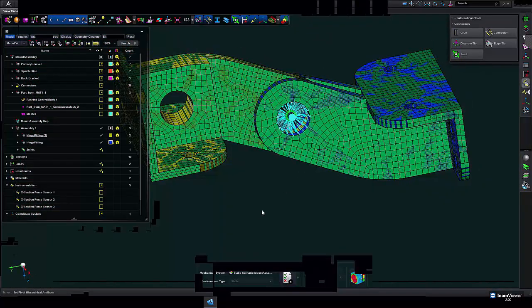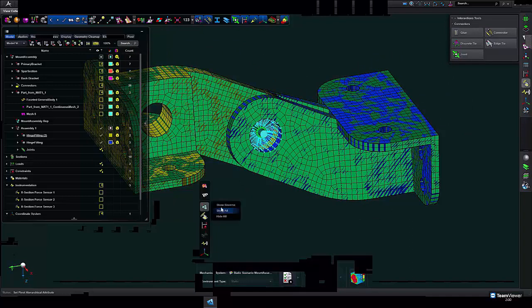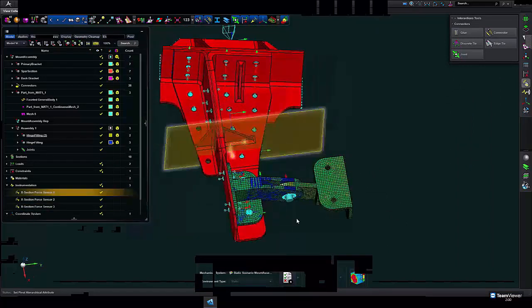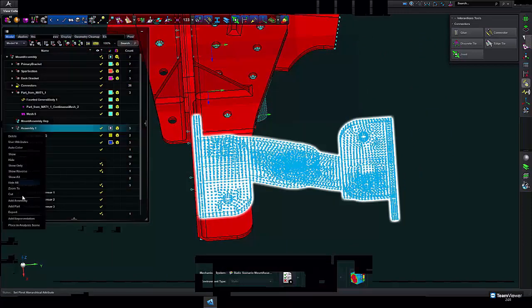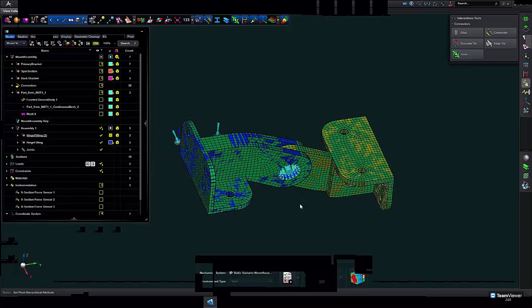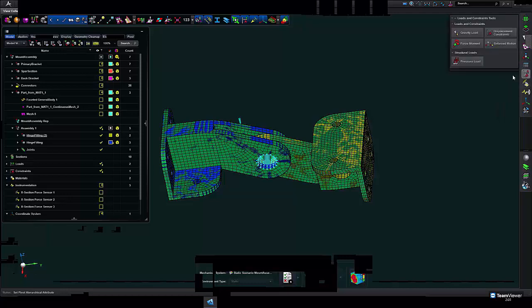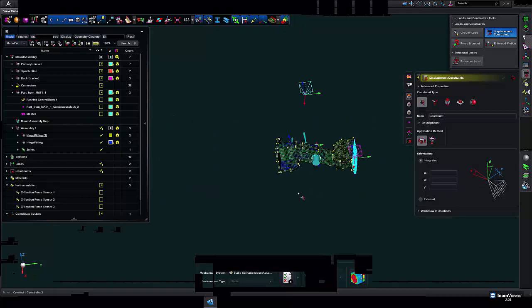Now, how do I make sure that that joint did in fact connect correctly? Now, remember, we sit actually with a much larger model like this, but I don't necessarily want to reanalyze the full model just to check that this single joint has been connected correctly. So what I can simply do is run a modal analysis just on this portion, and I'll just fix the one component so that I don't have too many degrees of freedom or rigid body modes.